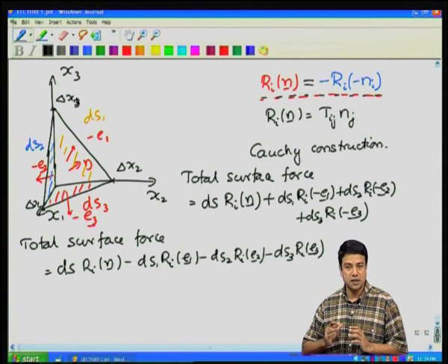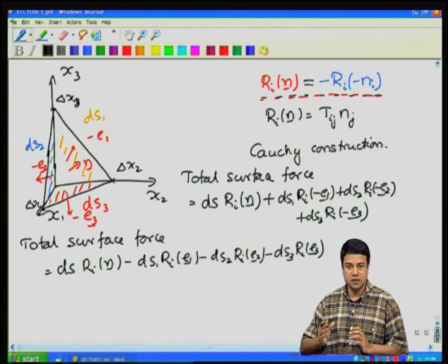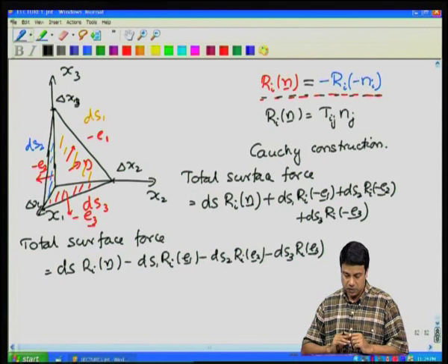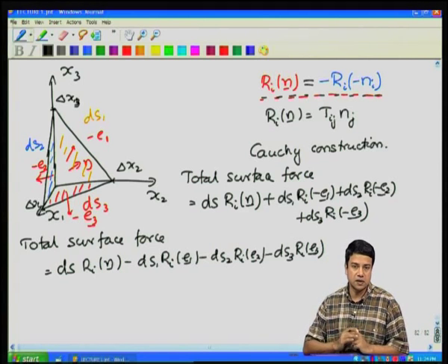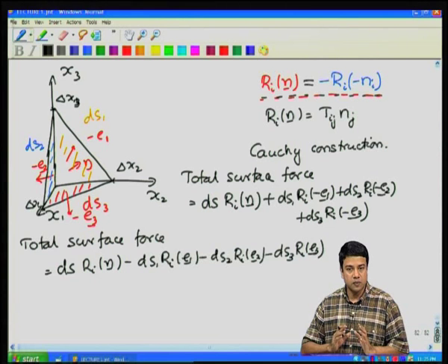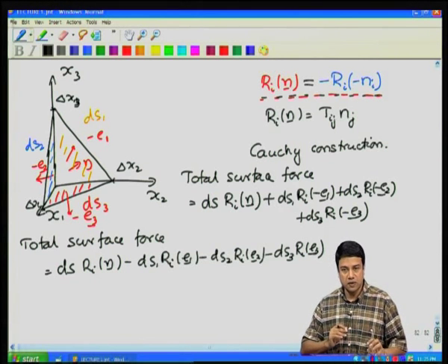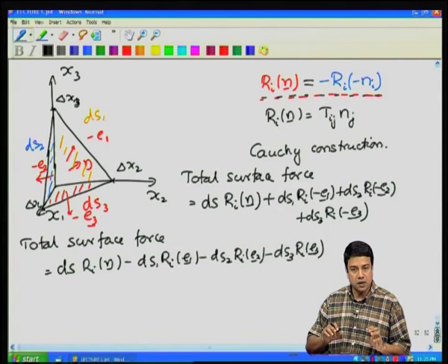As delta x goes to 0, delta x cubed goes to 0 much faster than delta x square, because the ratio of the surface to volume goes to infinity as delta x goes to 0. So, as this volume goes to 0, delta x cubed goes to 0 much faster than delta x square, which means that the momentum conservation equation with these volumetric and the surface terms will continue to be valid in the limit as delta x goes to 0 only if all three terms go to 0.